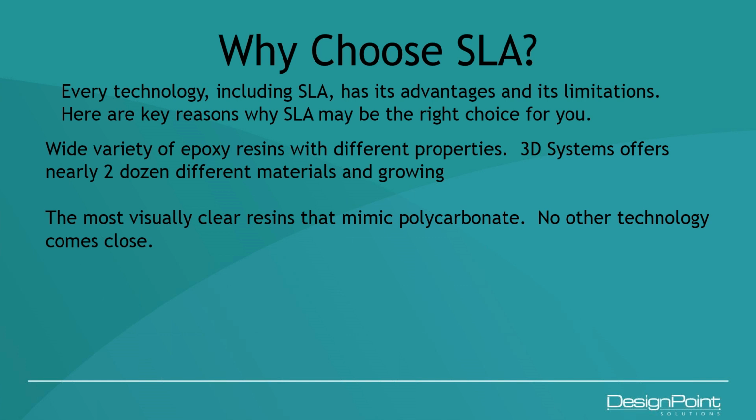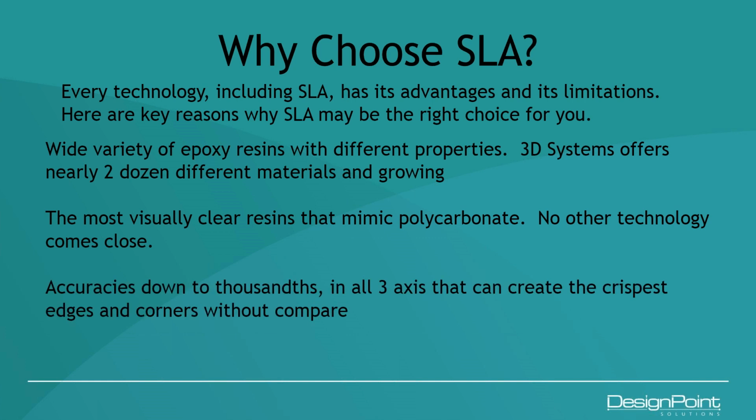The SLA is also incredibly accurate. We have accuracies down to thousandths in all three axes, and it can create the crispest edges and corners without compare. So even though the specifications of what we call the PolyJet or multi-jet technologies rival that of SLA, it can't compare when it comes to the edges and corners that are created using SLA technology.